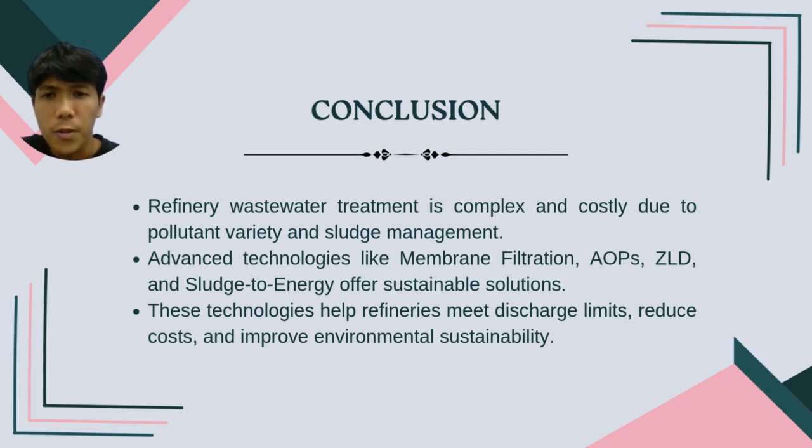So for the conclusion, refinery wastewater treatment is complex and costly due to pollutant variety and sludge management. To address these challenges, advanced technologies like membrane filtration, AOP, advanced oxidation process, ZLD, zero liquid discharge, and sludge to energy offer sustainable solutions. And these technologies help refineries meet discharge limits, reduce cost, and improve environmental sustainability.